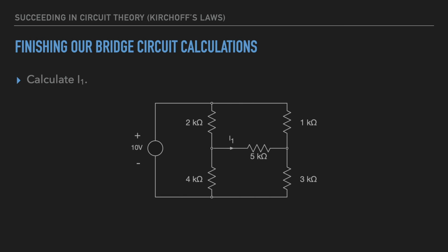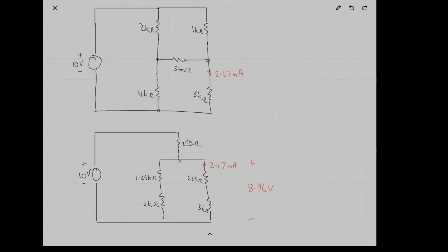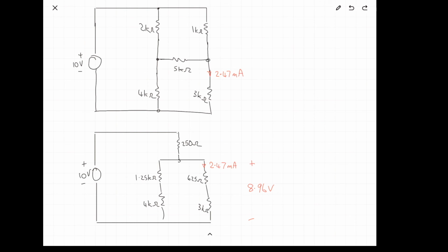Here is our bridge circuit from the previous 2 videos. In the resistance video, we calculated the current flowing down the 3 kilo ohm resistor. We'll now go to a diagram of the circuit as we left it. Here's the original circuit up top, and then our converted circuit, using the delta to star transformation, on the bottom with the values that we finally calculated in the previous problem. There's not enough yet on the top diagram to calculate the current that we want, which is I1.